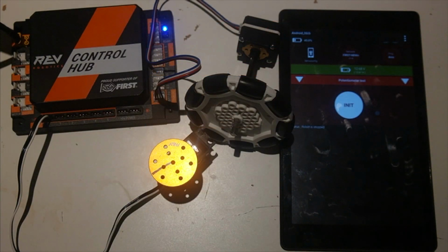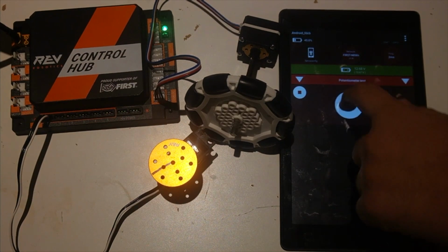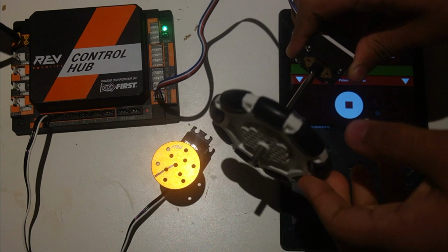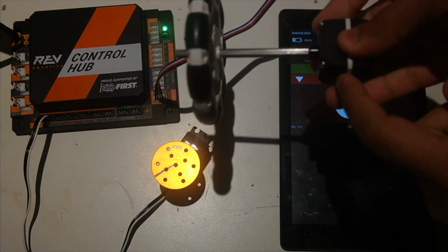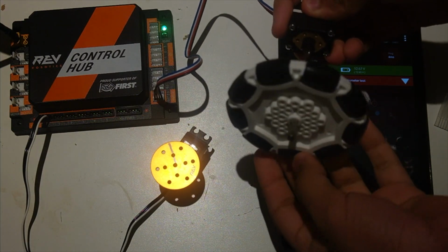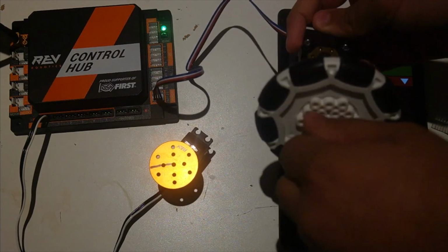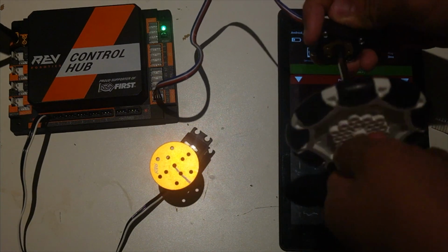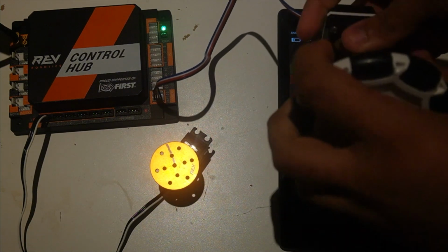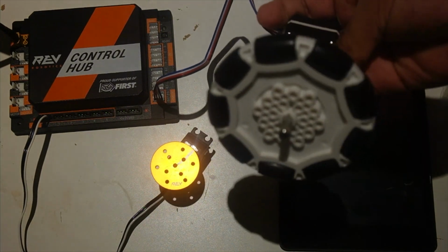Now I'm going to show you this. So first I'm going to select potentiometer test, and I'm going to hit init and play. Now you can see right now the servos immediately started moving. I put this Omni wheel on the potentiometer just to show you when it's rotating. So you can see that as I rotate the Omni wheel more, the potentiometer starts to move more. And there's really fine control because the potentiometer is such a good sensor, it's really precise.